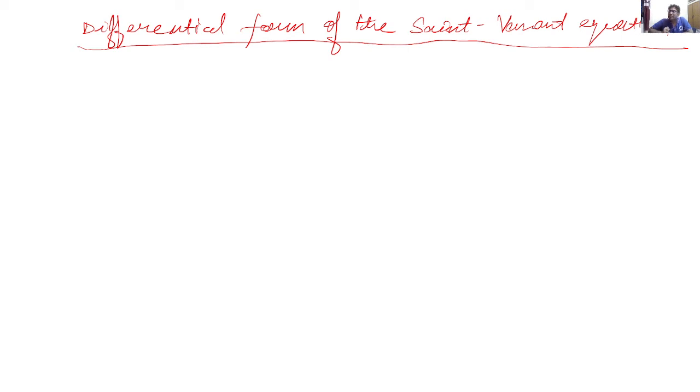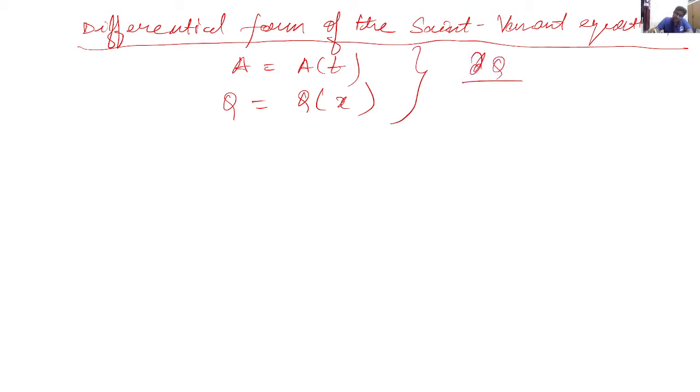It's very similar to the Navier-Stokes equation in terms of fluid flow. So it's a fundamental equation, and you need to know what it actually means. So the cross sectional area, let us suppose it's a function of time, and the discharge of the flow from the cross section, let us suppose it's a function of the length. Why am I coming into this? Because its central line equation is nothing but del q by del x plus del a by del t.